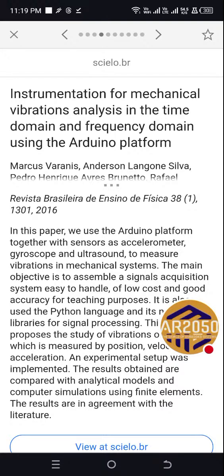When it is vibrating, just grab the data, throw that data on your Python or MATLAB, and do some data analysis. Do the time domain analysis, the frequency domain analysis, compare some data to find out the vibrations, try to swing the fan, the motor, try to do some knocking and see the pattern changes. So do that. If you want to grab the skills of signal processing, this is a good one.